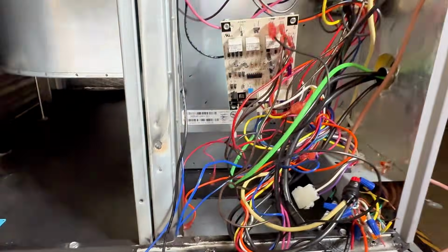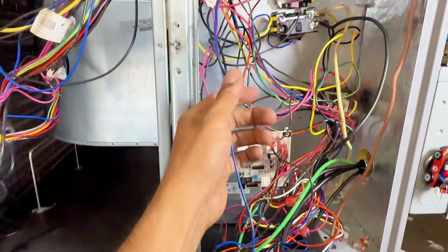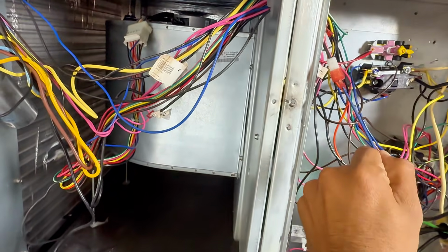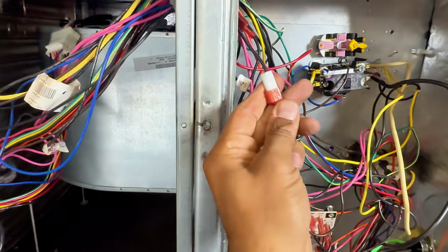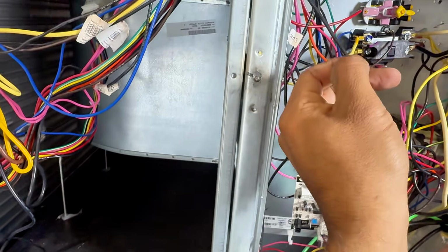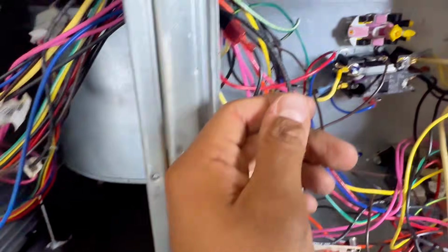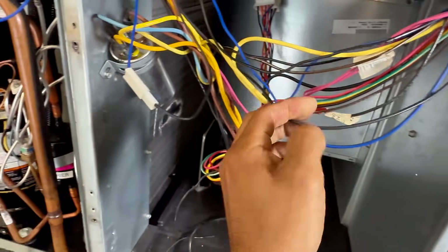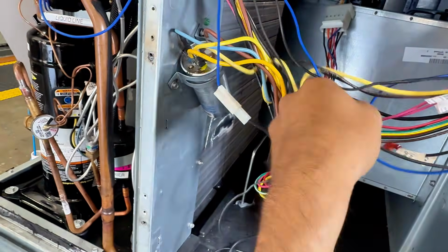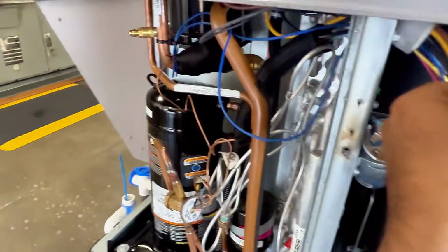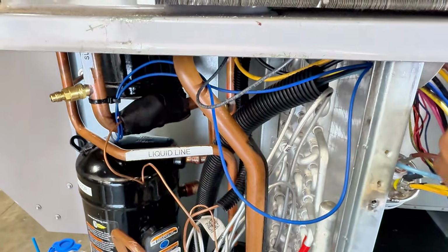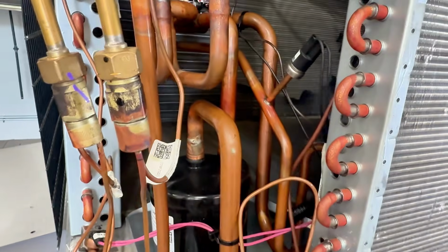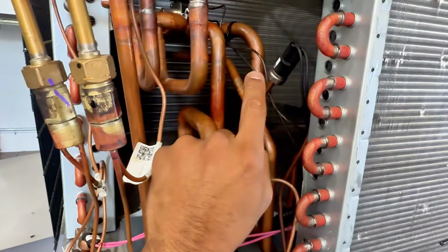So the blue wire, right? Let's follow the blue wire here. It goes to that one, and then that one, you see, it gets connected to a black one. If I follow that black one, if I pull on that wire, where does it go to? If I pull on that wire, okay, is this wire here? Okay, just bear with me, be patient right here. Okay, so that blue wire turned to a black one, and this black wire, you see, is going through that high pressure switch.